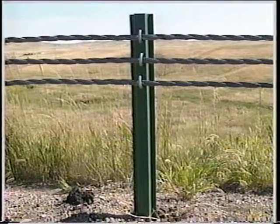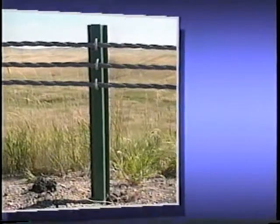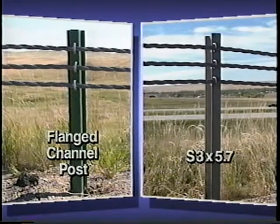The flanged channel post used in the South Dakota system weighs only 4 pounds per foot, 40% lighter than the standard S3 by 5.7 post. A flanged channel post and soil plate made of re-rolled rail steel would cost about half as much as the standard G1 post and soil plate. The South Dakota cable system cost almost $1 per linear foot less than the G1 guardrail.